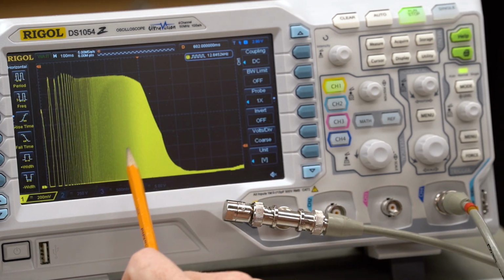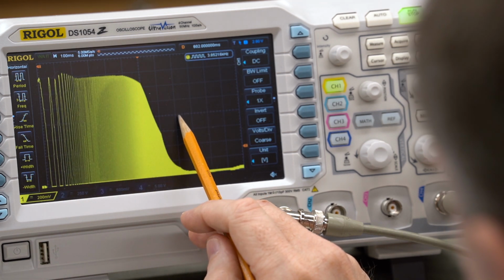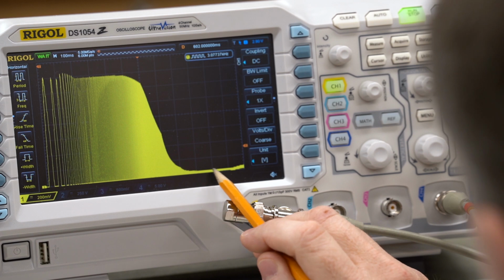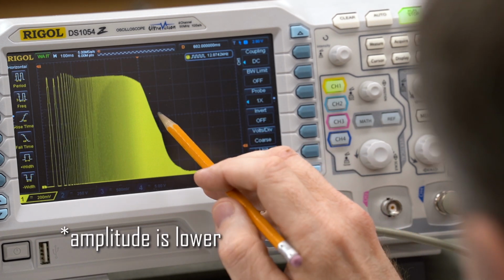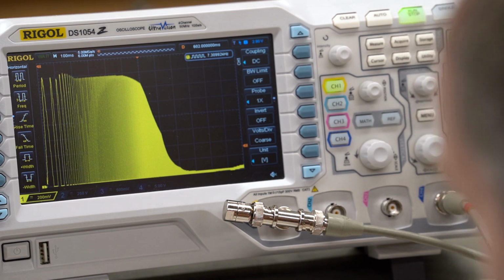And again, this is not a spectrum analyzer, so this is not the easiest way to read it. You know, this is not the best tool for this job. But you can see we've shifted the frequency considerably to the left, and you'll note that the residual amplitude down here at the higher frequencies is lower. So the total attenuation is lower, and the point at which that attenuation starts has shifted downward in the frequency.